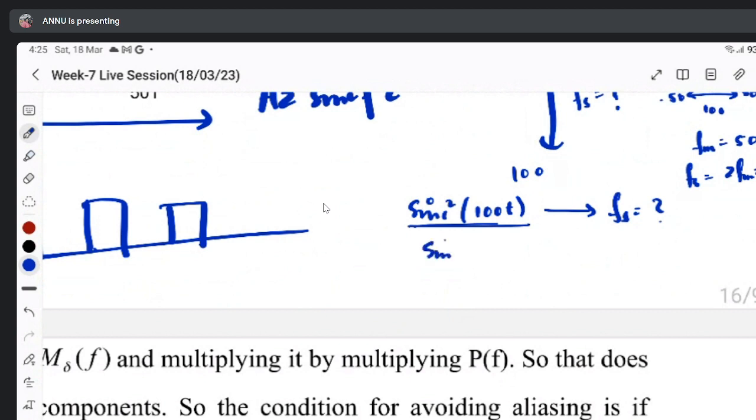So what should be for sinc(nt)? On similar lines, we will have 100n. Yes, right. So what you are saying here, in the sinc domain, you just multiply the bandwidth by n times, right?